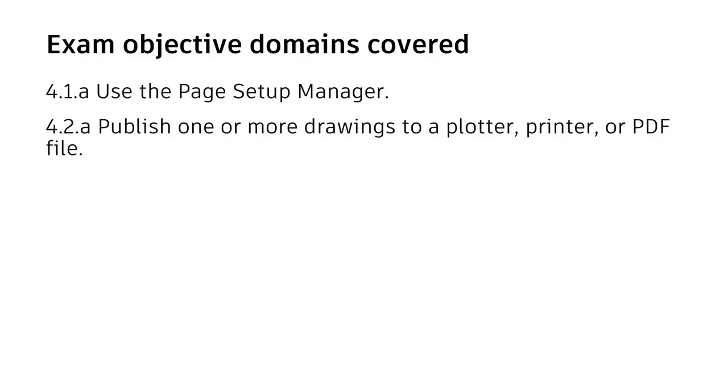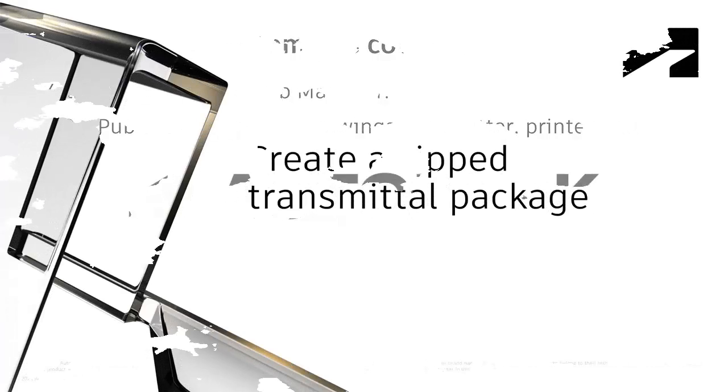In this lesson, we used page setups to control how layouts would be plotted and used the batch plot tool to plot several layouts in a drawing. Batch plot can be used to plot more than one drawing and more than one layout.